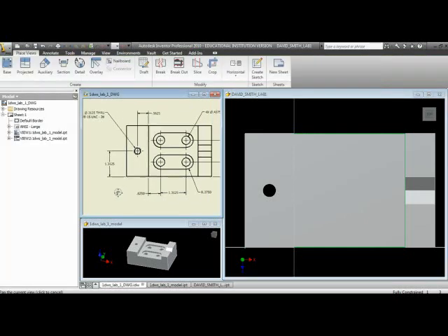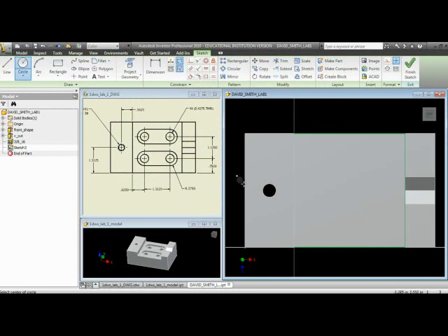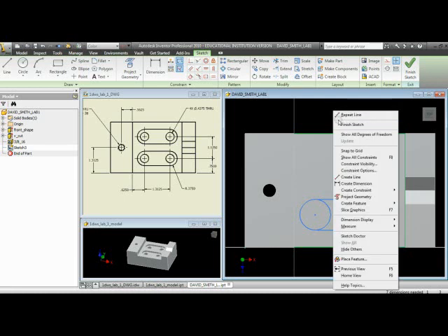Okay, so then what I'm going to do, I personally like to put in circles instead of arcs for these particular characteristics here. So I'm going to go in there and put in a circle. And it doesn't matter where I locate it. Done with that, and I'm going to put in some lines. Now, I want that line to be tangent, and there's my tangency. But it didn't do it, so there you can see the tangency there, and there's going to be a tangent there.